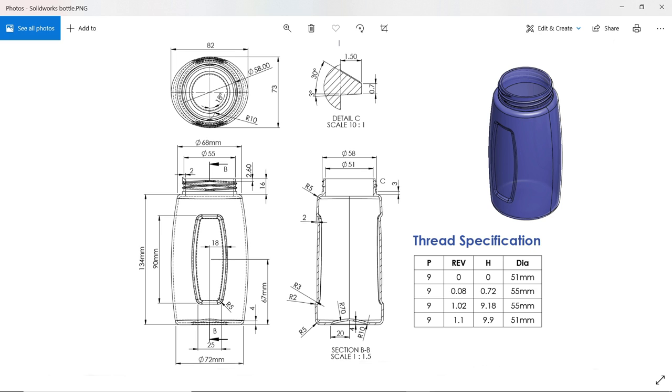First we will close the upper hole, then we will create this one. See this depth inside 2 millimeter, okay, 90 by 25 millimeter, and there is one radius, both corners 18 millimeter from center point, and this radius also inside, you will see R3 and R2. I'll show you in detail.